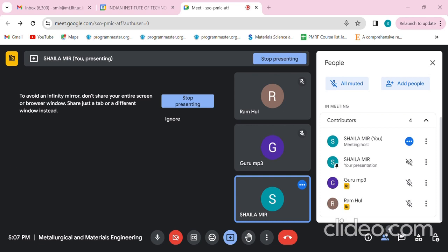These are the questions that are based on your phase diagram. The first question says that solidus and solvus lines are the boundary between. So you know we are talking about binary phase diagrams, where we have two components A and B, which are forming a binary phase, and they are forming some solubility diagram. Like we have a phase diagram.